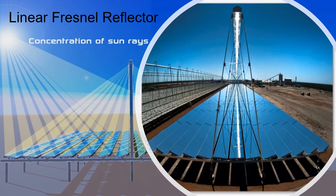To summarize, these concentrating collectors use reflective surfaces to concentrate light onto a receiver. The surfaces are either flat or parabolic depending on their type. These concentrators can increase the incident sunlight by hundreds of times due to the large surface area of reflectors. However, some require sun tracking as only direct sunlight is absorbed by the receiver. Tracking can be done in one or two axes, creating a more precise path and producing more power. They work best in clear and dry climates for high temperature applications.